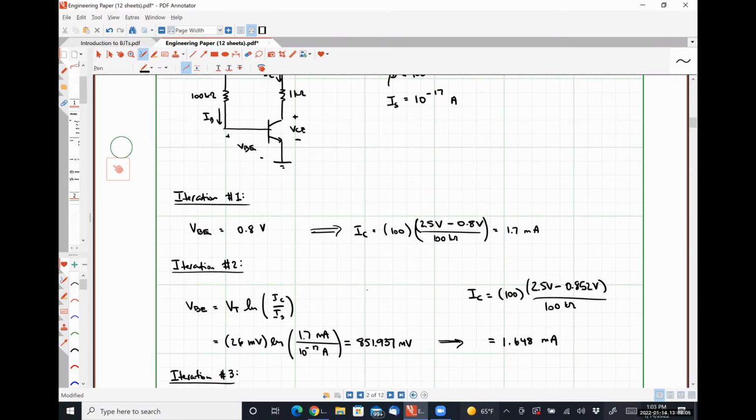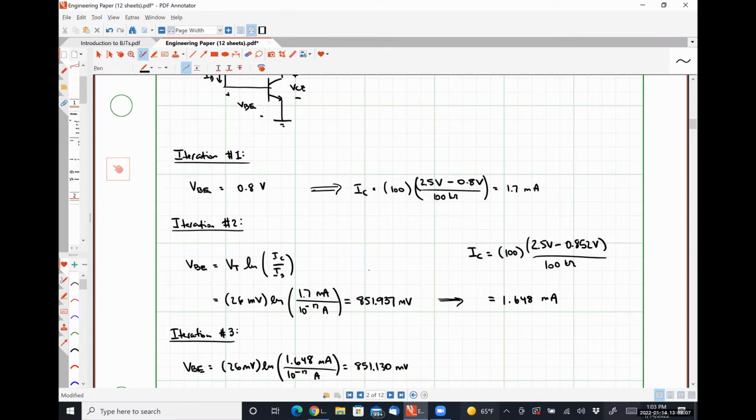That we could develop a single solvable equation using this guy and this guy, effectively. Substituting in this relationship for VBE into this guy gives us a single variable IC that we could use to calculate IC directly using a numerical solver on our calculator or whatever. And then from that, we could back calculate out what VBE is and know all the other quantities. So this is the, oh shit, my calculator doesn't work, or I have a peasant calculator or whatever reason method.